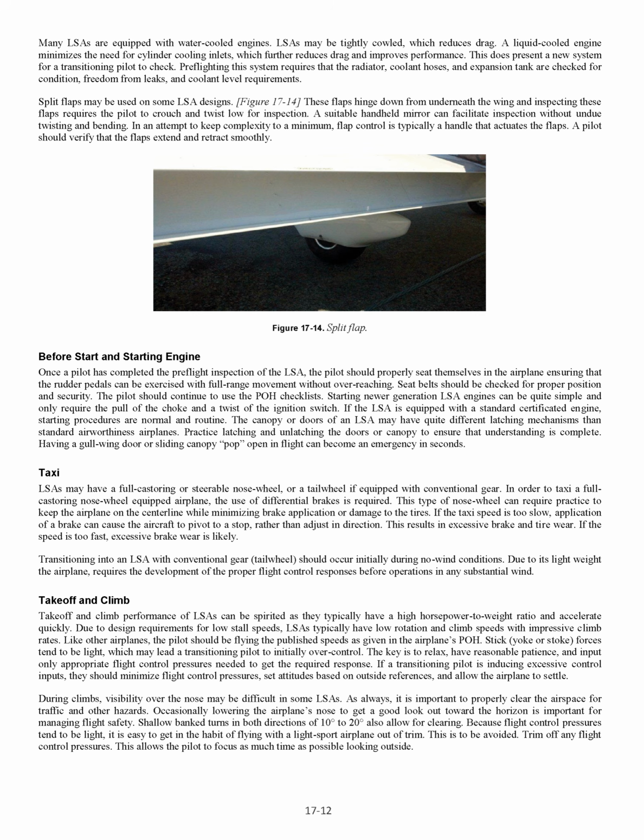The canopy or doors of an LSA may have quite different latching mechanisms than standard airworthiness airplanes. Practice latching and unlatching the doors or canopy to ensure that understanding is complete. Having a gull wing door or sliding canopy pop open in flight can become an emergency in seconds.